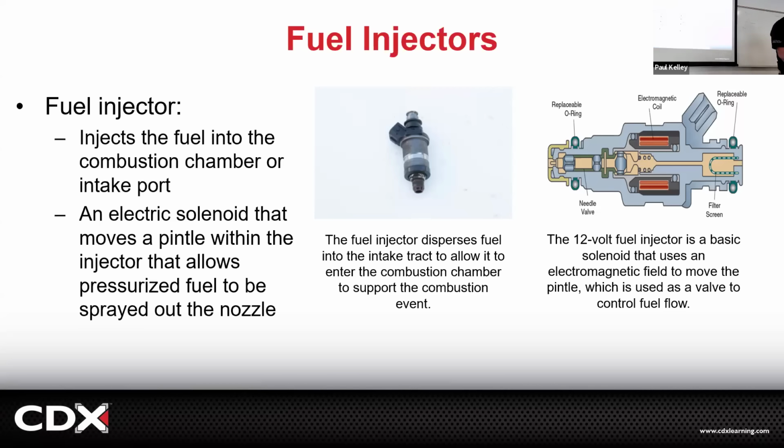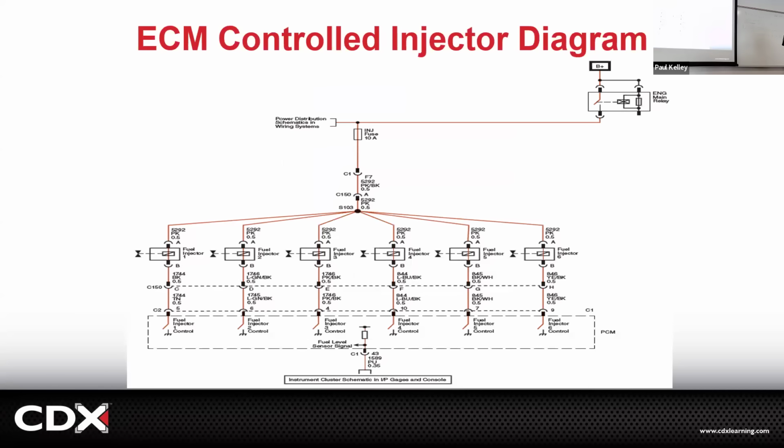If you wanted to get into that, you'd look at this. You'd be like, let me look at my diagram. From the relay, it's going to come down here and it's going to provide 12 volts to the injector. The PCM's down here. What's the injector providing? What's the PCM providing? Can you tell? It looks like voltage to me is coming from B+ through the main relay, through the injector fuse, and it's being applied the same voltage to all the injectors on the pink wire, circuit number 5292. I think the injectors have voltage all the time.